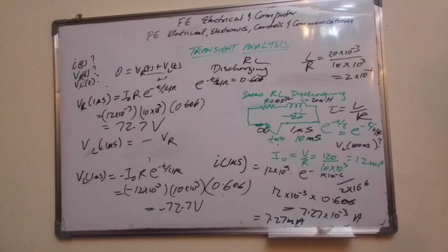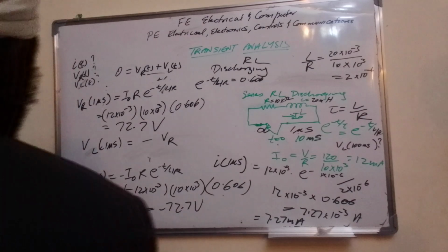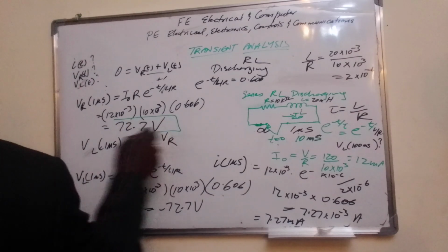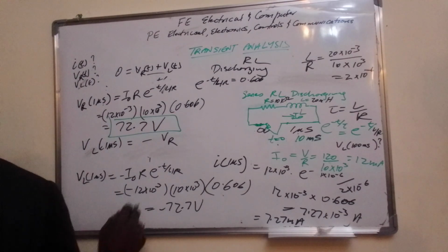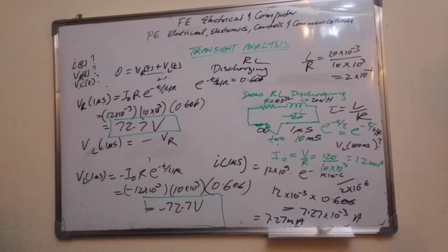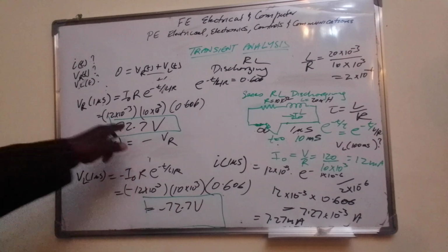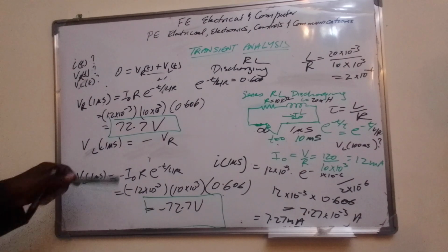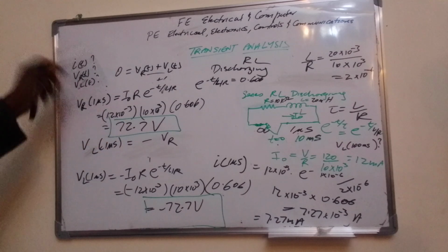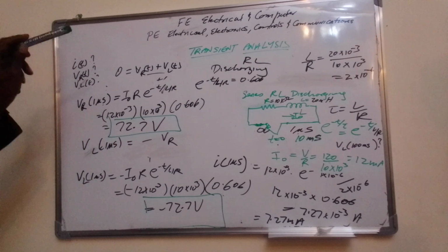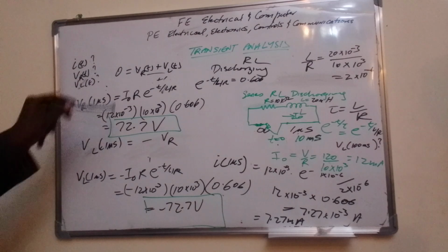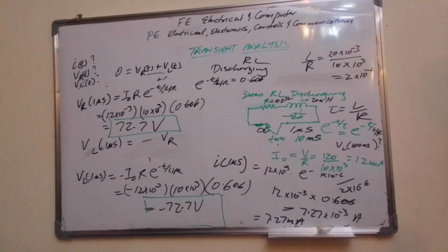So there ends our answer for both V sub L and V sub R. This is V sub R. This is V sub L. Discharging through the resistor, after a longer time this value will tend to go down. So maybe after 2 milliseconds you could assess and see how the value is decreasing.